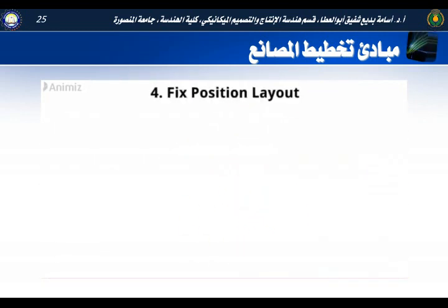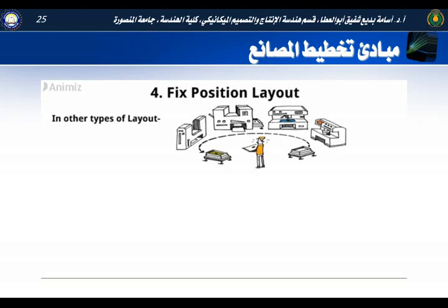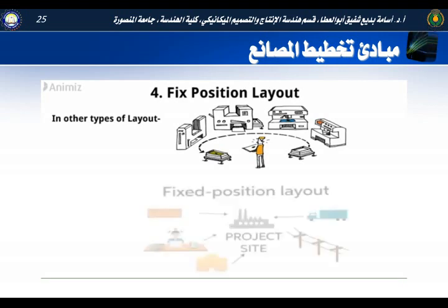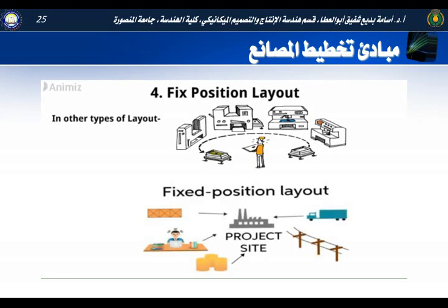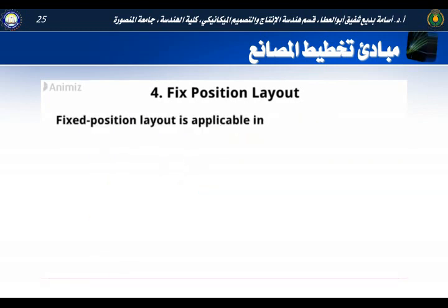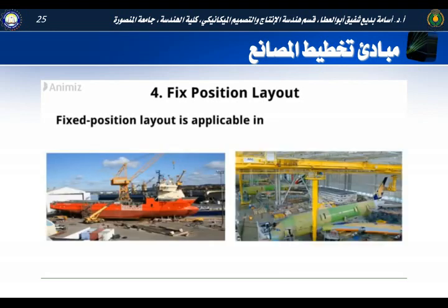4. Fixed position layout. In other types of layouts, the product moves past the stationary production equipment, but in a fixed position layout, the product is kept stationary, and equipment moves around it. Fixed position layout is applicable in shipbuilding, aircraft manufacturing, etc.